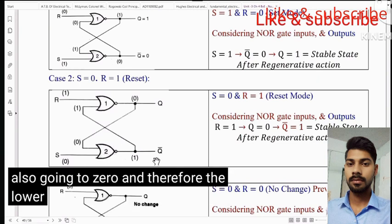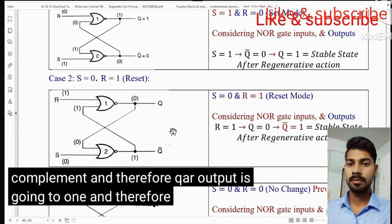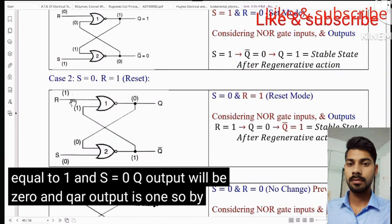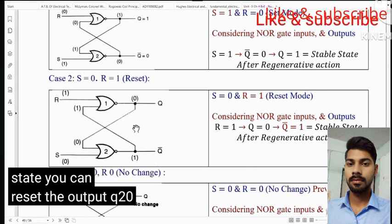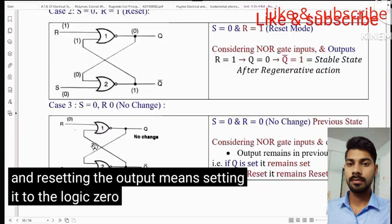Therefore the lower NOR gate output is 0 OR 0 complement, and therefore Q bar output goes to 1. So when R is equal to 1 and S equal to 0, Q output will be 0 and Q bar output is 1. By making reset input R logic 1, you can reset the output Q to 0. Setting of output means setting it to logic state 1, and resetting the output means setting it to logic 0 state.